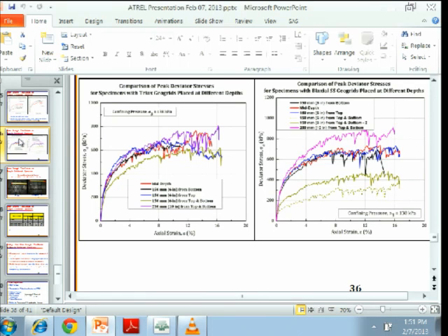Well, these are fairly clean ballast. If we are using fouled ballast along with geogrid, the test results may be different. So more research is needed. Yeah, I would say clearly if you have a poor quality aggregate, I would probably agree with you. But in this case, why would you put a good aggregate with a geogrid? It makes less sense to me.